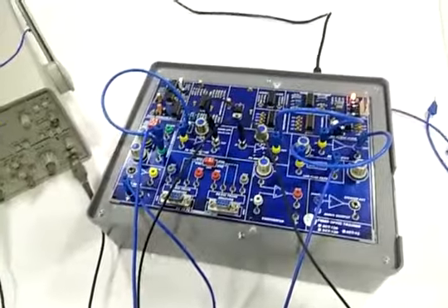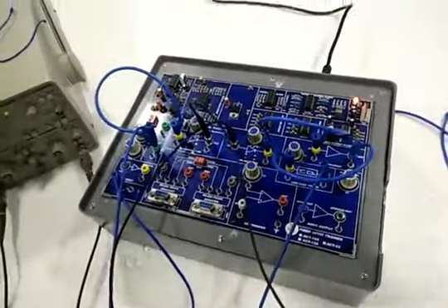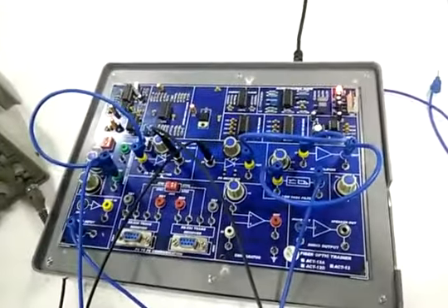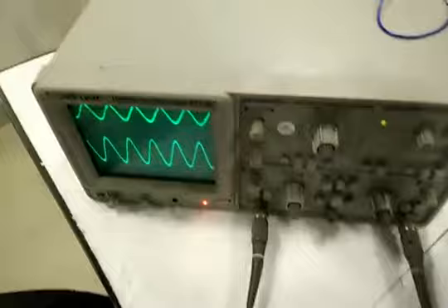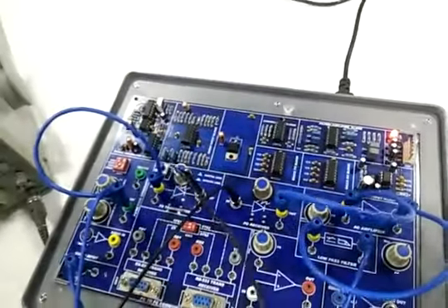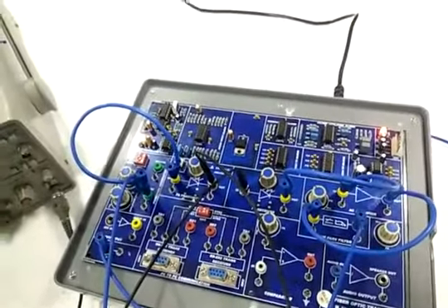The other experiment is measurement of propagation loss. Keep the setup as it was for analog link. Measure the output voltage. Now change the 1 meter fiber optic cable with a different length of fiber optic cable such as 2 meter, 3 meter or 5 meter, and measure the corresponding output value.